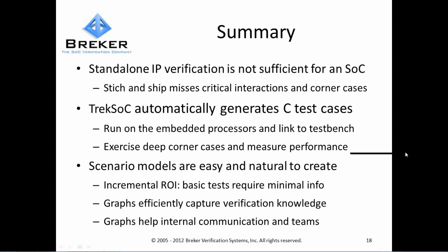An SoC might have a display unit, right? You've got to see something on the screen. That display unit might be displaying information from the output of the image processor if you're looking at a photo, or it might be using data from the output of a video decoder if you are watching a movie. The image processor might get data from maybe a USB dongle or maybe from an SDIO card, to static storage locations. And the video decoder could also be getting data from either of those locations. And what we have here is a graph of possible data flows through the system.